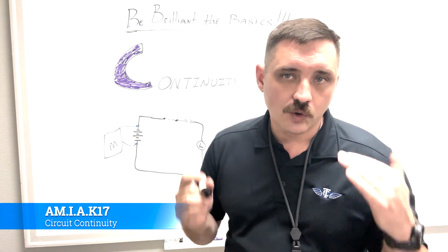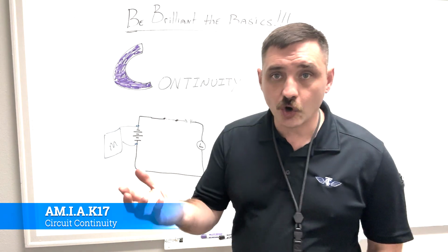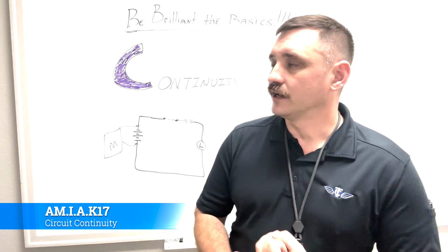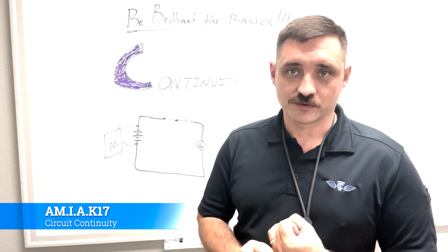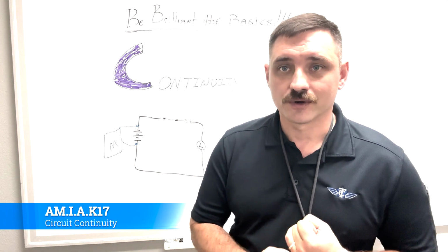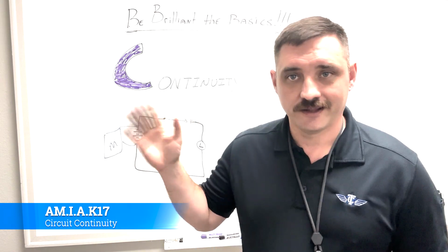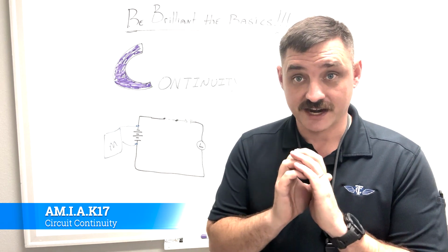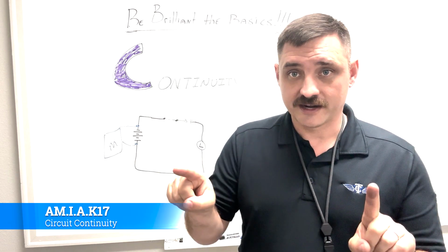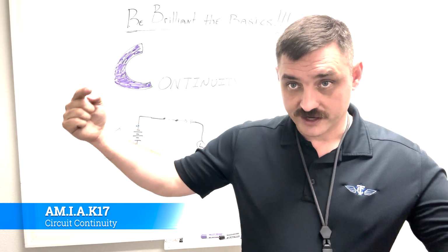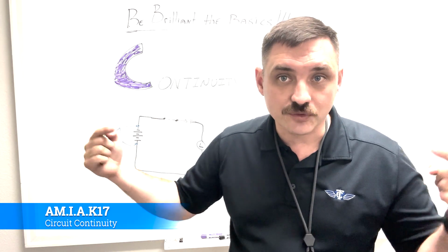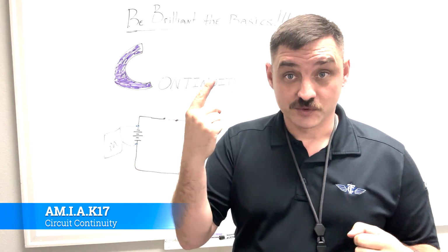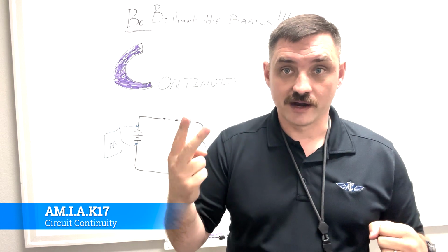So let's talk about what some of your common culprits are whenever you fail a continuity check. Well, for one, something's not connected right. I can't tell you how many times after some sort of rework, especially wiring rework, continuity says, hey, look, these things aren't connected. You'll say, oh, it's in this connector right here. We know through the wiring diagrams that it connects to these connectors over there, and you start ringing wire to wire. They call it end-to-end ring outs, where you just go through the whole thing, and eventually you'll find it won't be just one wire that's not ringing. It's two wires, and it's because they're swapped.